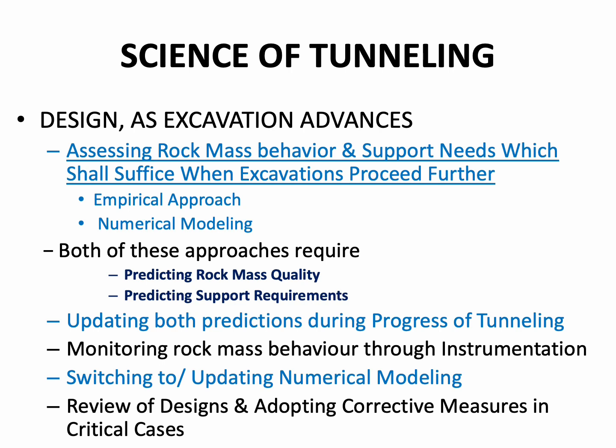Monitoring rock mass behavior through instrumentation. Because the height of the excavated caverns would be large, the monitoring of rock mass behavior through instrumentation also becomes a necessity.